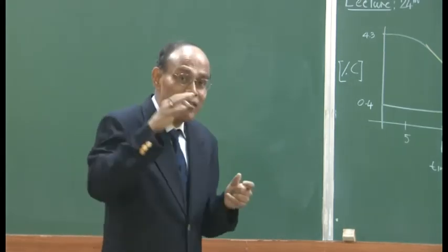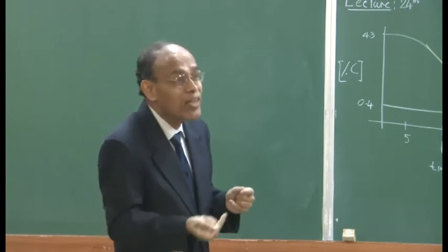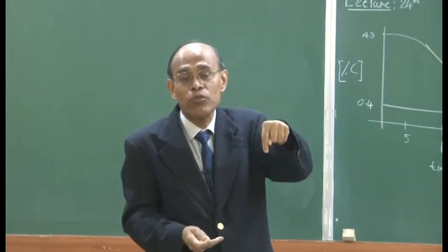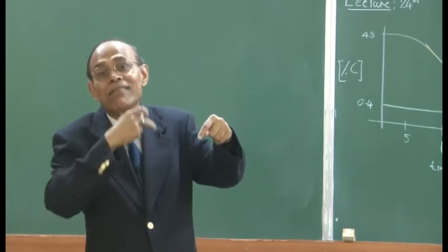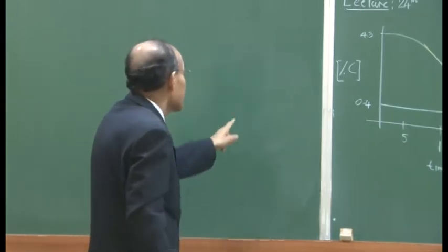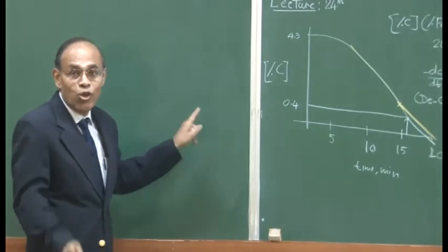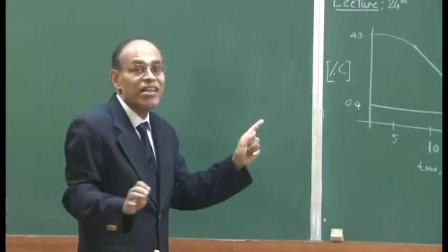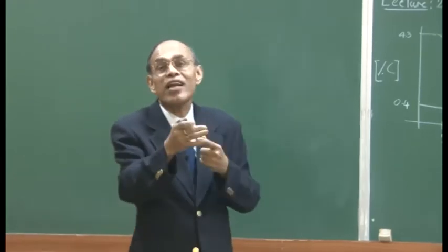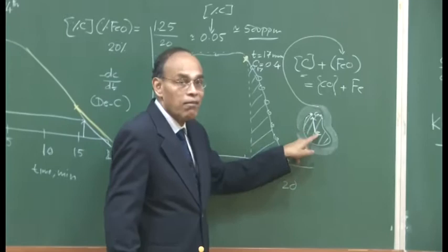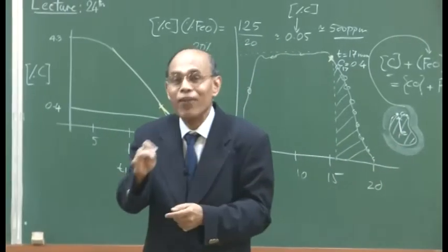So, it is virtually whether you are injecting from the bottom, or from top and bottom, or from the top, that will determine the stirring intensity in the system, and that is going to determine the rate constant K. So, the thermodynamics is absolutely identical, but the kinetics are different, and that is why the efficiency of reactions, this transport, these are going to be different in different systems.